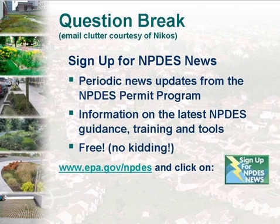As we move into impaired waters, though, impaired waters that we're writing TMDLs for, those TMDLs are based on loads, at least to start with, and then it is up to the writer of the TMDL and then the permit writer to translate those loads, which are daily loads, so pounds per day, basically, or kilograms per day, into a water quality-based limit in a permit. And that limit can actually take a bunch of different forms.